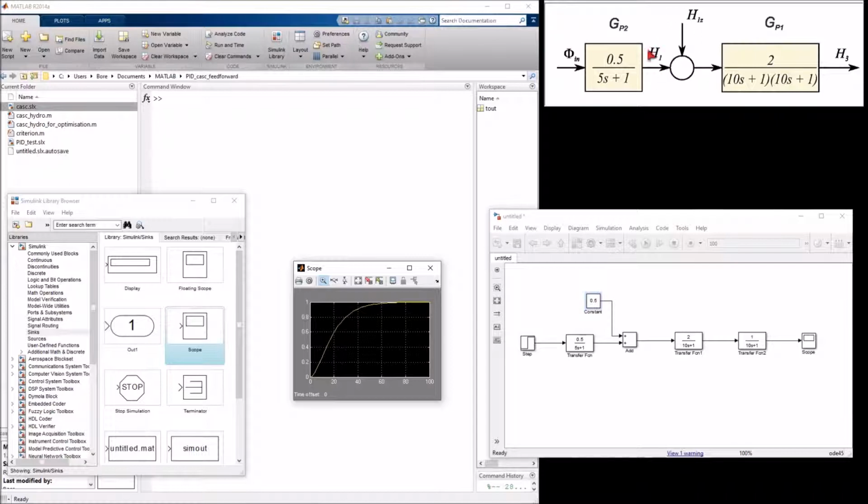So in the first tank, the level is changed by 0.5 meter, and in the third tank, the level is therefore, due to this disturbance, changed by 1 meter. The gain of this path is 2, but as the disturbance signal is 0.5, it's correct that the increase of this signal is 1.